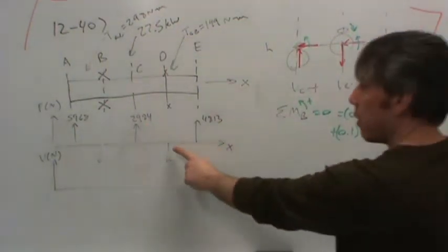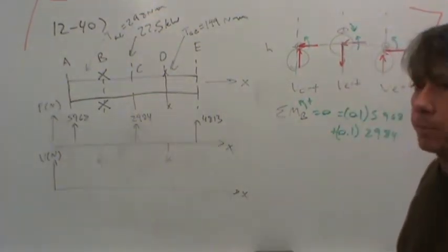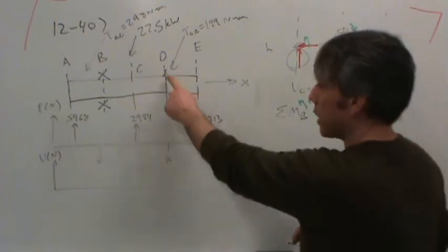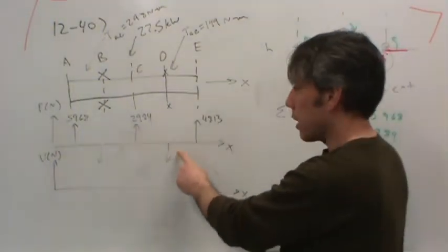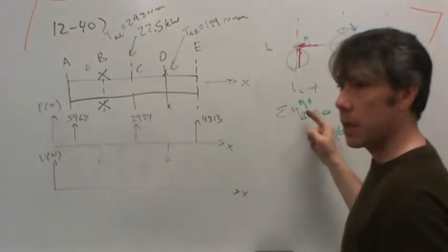Okay. Tell me how I would add this term. Is that going to cause a positive or a negative moment? The reaction at D. Negative. It'll be a negative moment, that's right, because it's going to twist the shaft clockwise, which is opposite my sign convention, right?